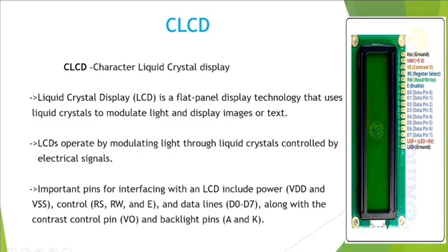Important pins for interfacing with LCD include power, VDD and VSS, control RS, RW and E, the data lines D0 to D7, along with the contrast control pin VO and backlight pins A and K.